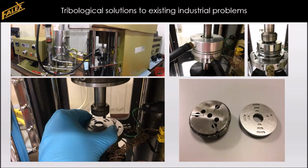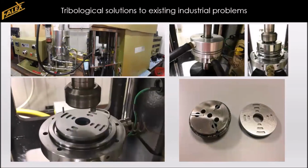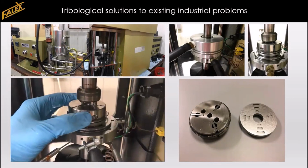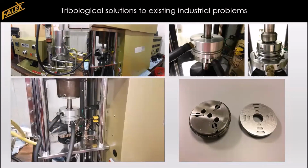These test specimens can be fitted in the Falex multi-specimen machine, and they are designed to recreate the contact conditions, a sliding line contact of a vane pump. These are then set up in the test machine. And of course, an oil reservoir is placed around this, and we use a recirculation of the oil to lubricate the contact.